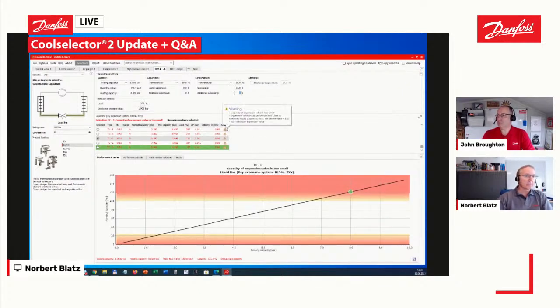Then you can see we get a warning in all of the sizes, and the warning says here that at the outlet of the valve, the flash gas is below the recommended minimum, and the recommended minimum of 5% is already quite low. So my recommendation would be to keep a pressure drop and subcooling under these conditions to get a quality at the outlet of the valve of not below 20%.